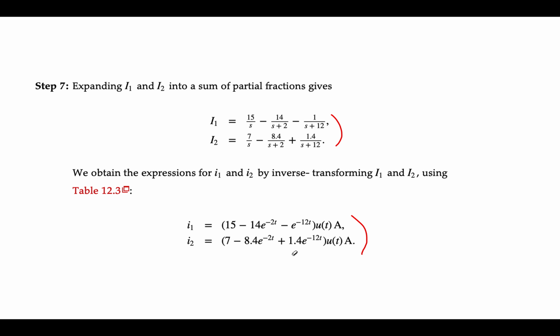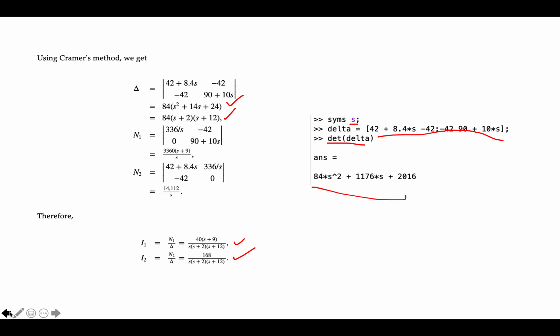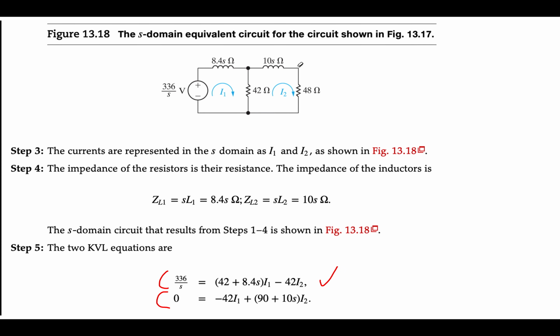It's got two time constants because I have two inductive storage elements. If I had a third out here with an inductor and a resistor, these are ladder networks. They're called ladder networks. If I had a third out here, I'd get even a third time constant. And I would get a higher order differential equation. I'd get a higher order polynomial in S. So it would become quite a bit more difficult to solve.